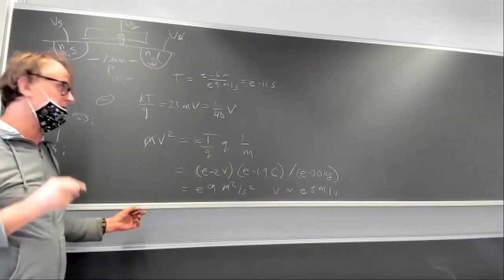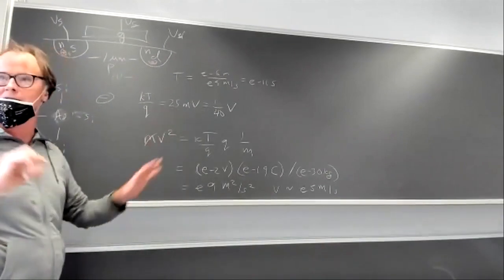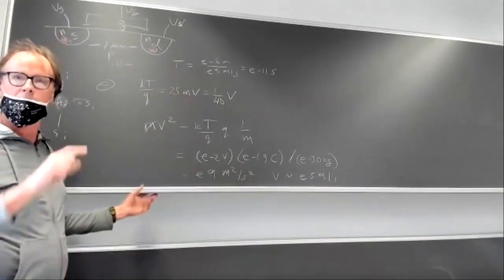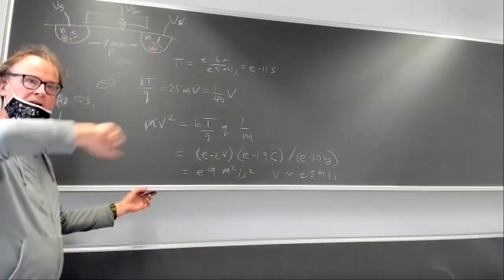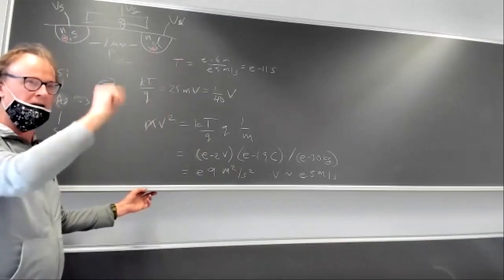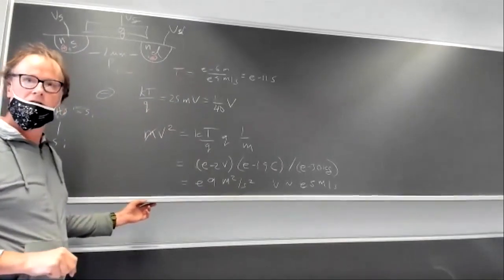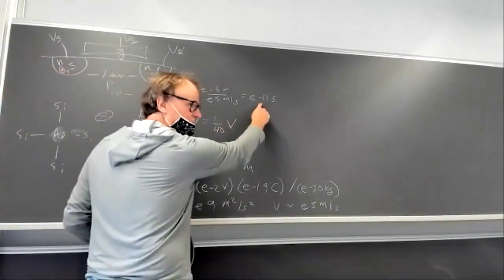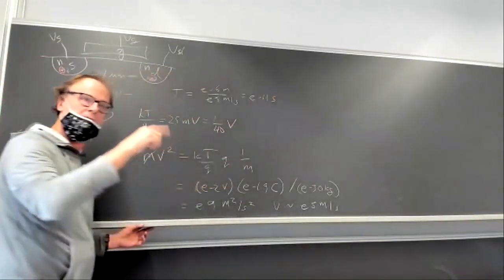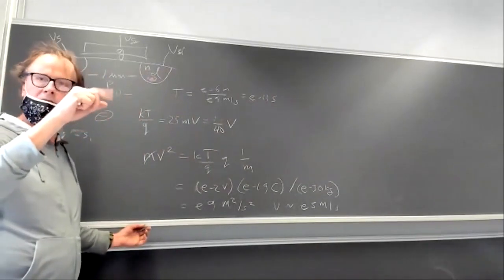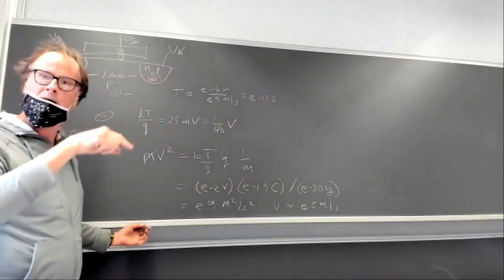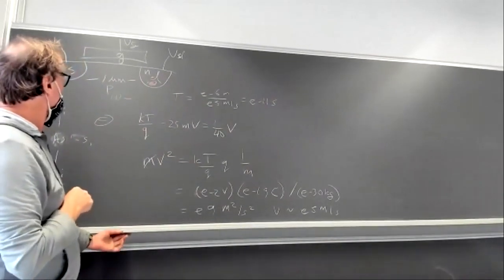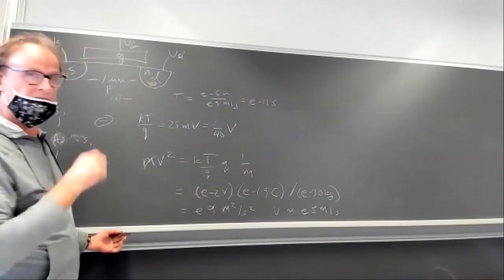I'm doing that because I want you to understand what the scale of these things is, how fast things are moving around and what time scale you're talking about. That's 10 picoseconds if it was moving in vacuum, freely moving and not colliding with stuff. So it's a very short time. That corresponds to a frequency of 10 to the 11 hertz, switching frequency. That's why silicon logic can work so fast, right? Because it's a short time it takes the carriers to cross the channels. I don't know if that's helpful.